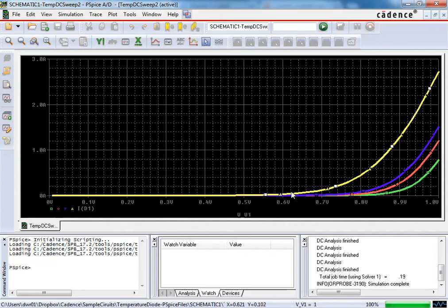So actually what we can notice here is that at lower voltages we have more current at higher temperatures, which is maybe a little bit different than the example we did in class the other day. However, remember these are actual diode models that are much more extensive than the ideal current and voltage relationship, and I can show you what we mean by that in a second.